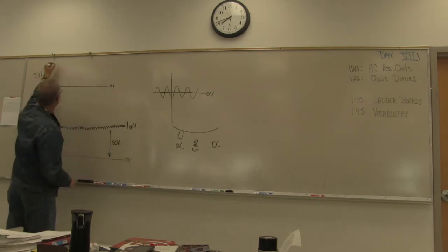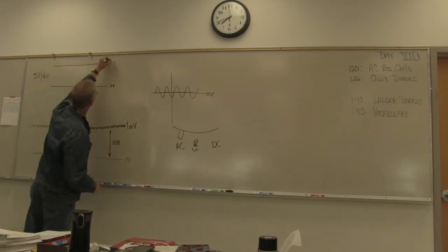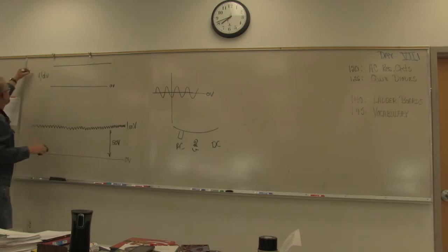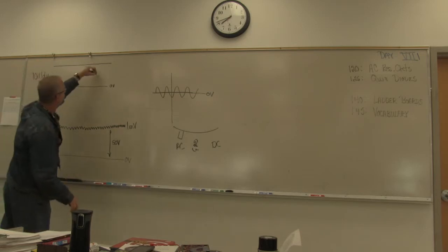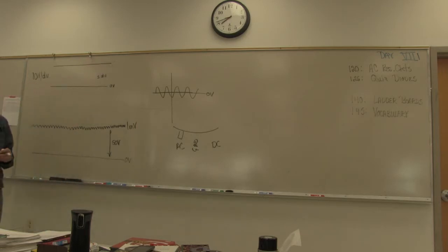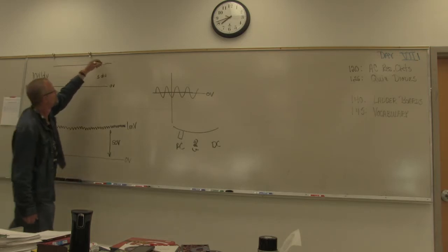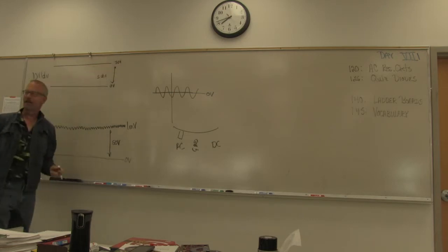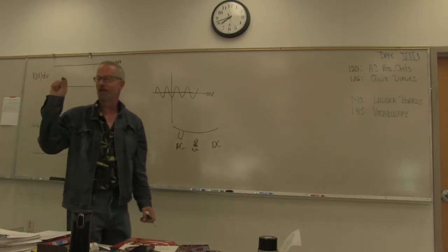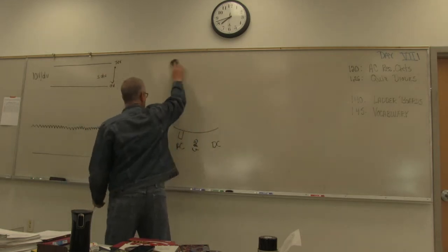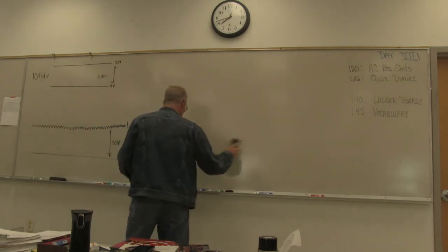0 volts, 5 divisions. I will see a flat line here at, now wait a minute, not 5 volts per division, must be 10 volts per division. 5 divisions, I got a flat line. Okay, how big is 1 millivolt on this magnification? If this represents 50 volts on my screen, do you think for 1 minute that I'm going to be able to see that 1 millivolt? Okay, well, we can't do that, so let's put it on 1 millivolt per division.